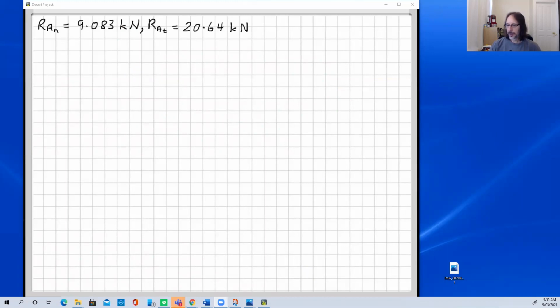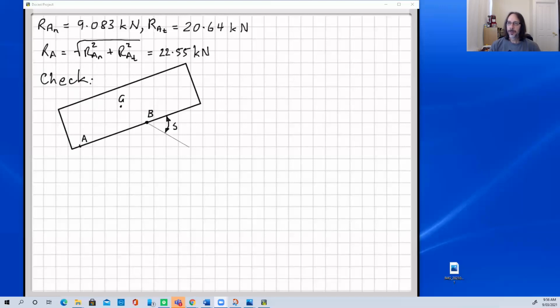Just repeating those on our next page for reference. So if you want to find the magnitude of that force, so if this is a design problem, you want to know what the total magnitude of the force acting on that pin is, so you can select the right material and size for that pin. Okay, so you should know just square root of the sum of the squares to do that. So let's check our solution. I've just redrawn for you here the free body diagram.